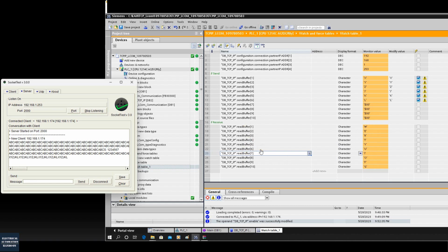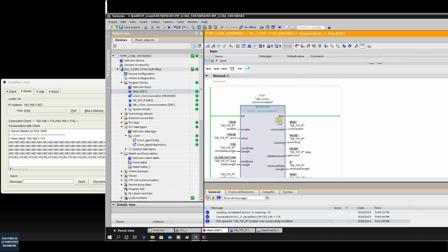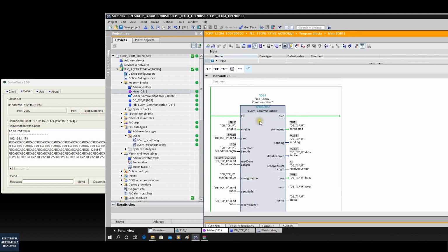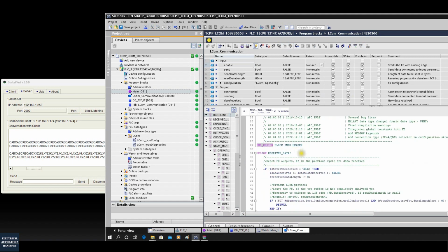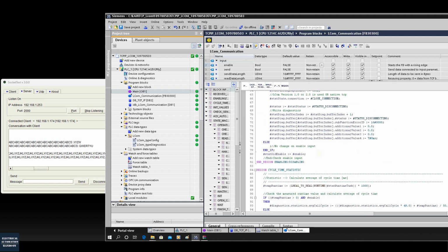The reason it can be dynamic is that in this function block, the receive function block is running in ad hoc mode. If we go into this function block, all the code is open, so you can learn these things yourself. This is the beauty of the Siemens function block. Most of the time, their function blocks are not sealed, so you can learn, or even troubleshoot what's going on there.